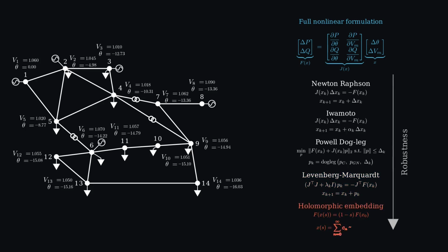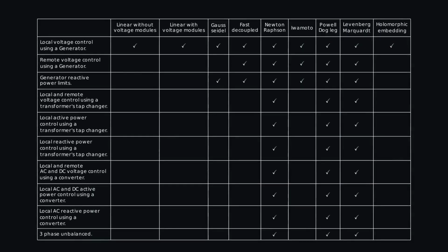Finally, the holomorphic embedding solver takes a non-iterative approach, expressing the solution as a power series in a complex embedding parameter and evaluating it analytically. It provides a globally convergent alternative that can solve difficult cases where traditional iterative methods struggle. This comes at the cost of some complexity, as any change to the formulation will require extensive reworking of the solver.